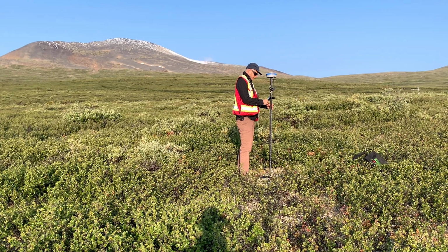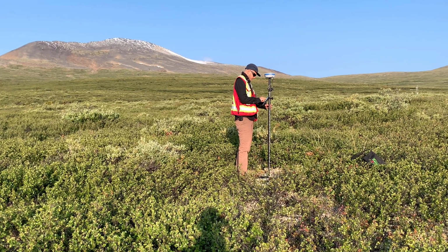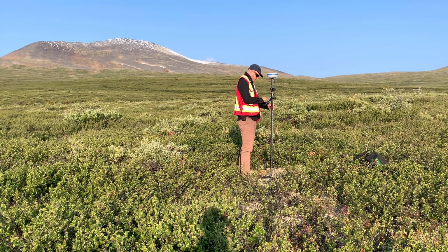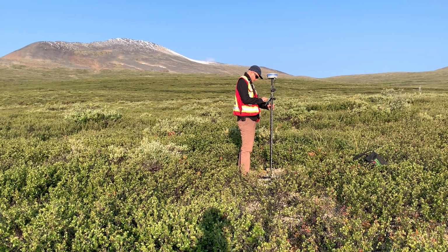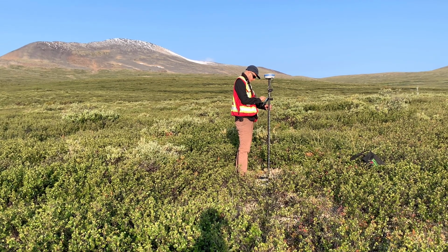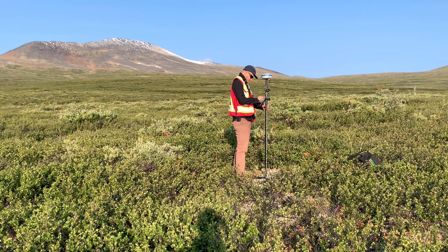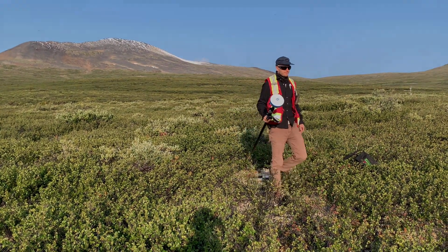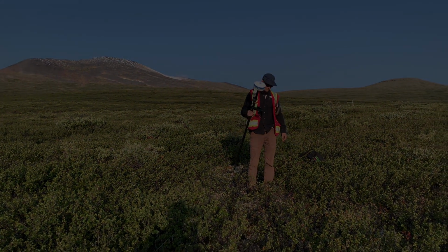These points allow for accurate georeferencing of the imagery, as well as compensation for any distortion which may occur in the course of image processing. It's important to note that the accuracy of any imagery that is produced cannot be higher than the accuracy of the location measurements for these ground control points.